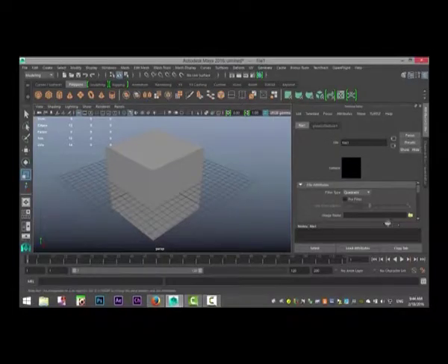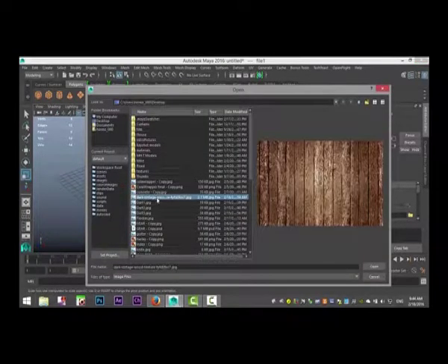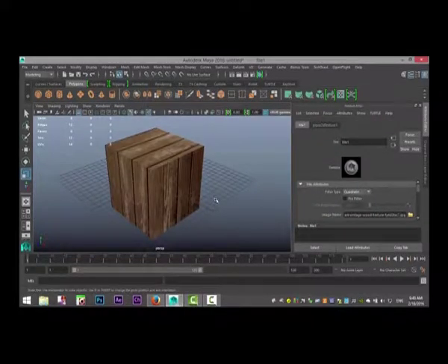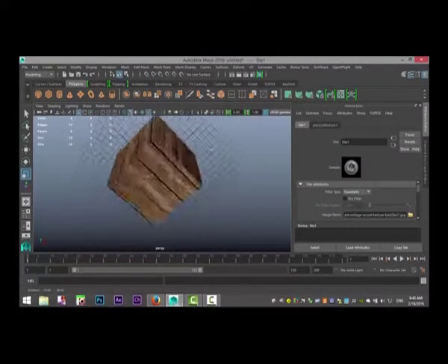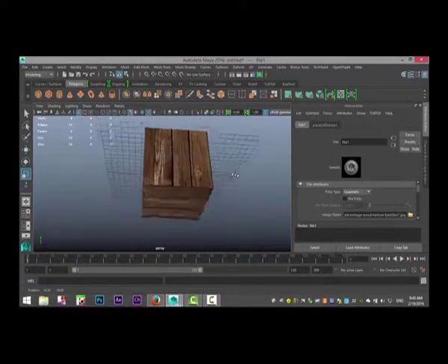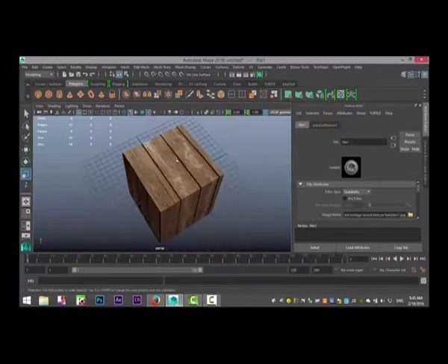The create UVs option assigns UV texture coordinates on the primitive for texture mapping. The various normalization settings fit the UVs within 0 to 1 texture space. Normalize collectively and preserve aspect ratio is the default setting.